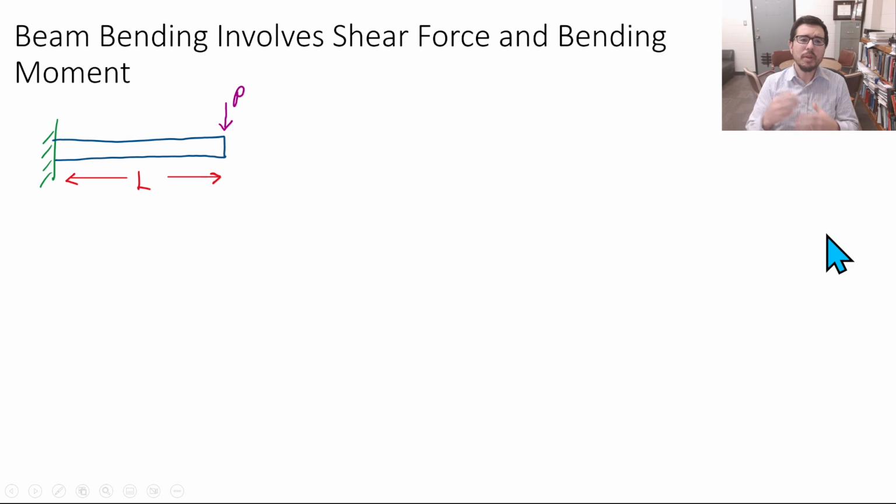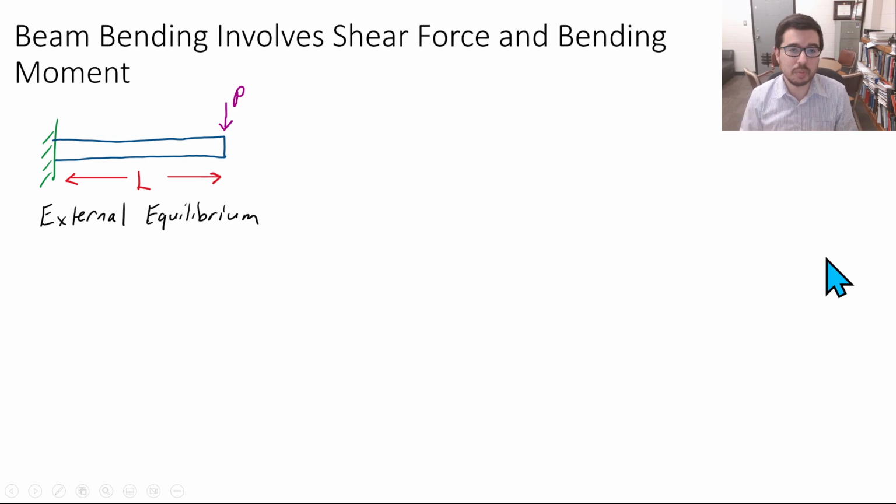So before we get into talking about strains and stresses, let's go back to being able to describe the bending moment and the shear force across a beam. This is a fairly straightforward example, and we're going to use the integral or differential forms of dV/dx equals w and dM/dx is equal to V. The first step is to create the model, which we've done already.